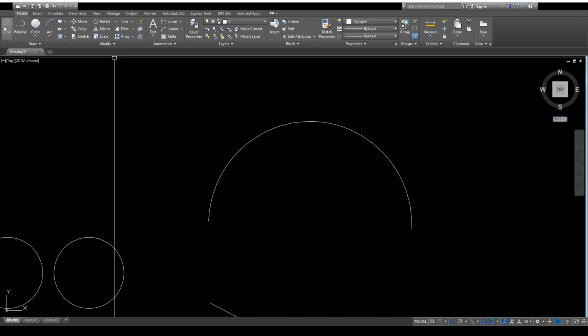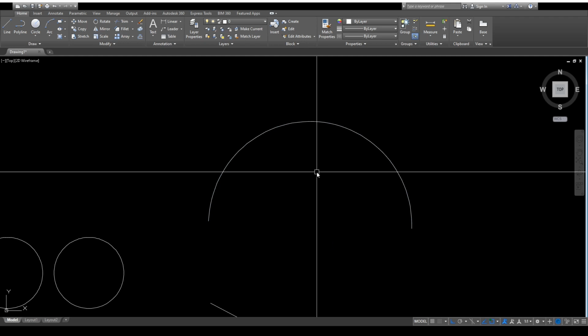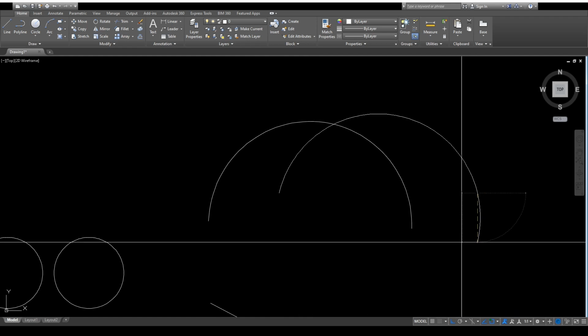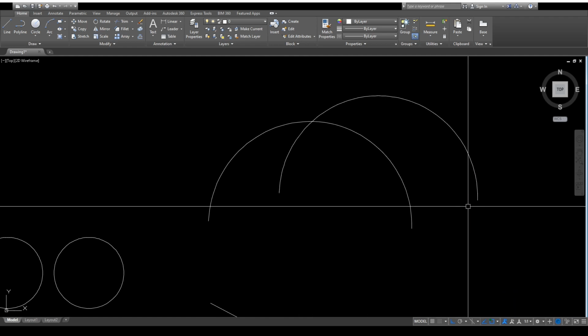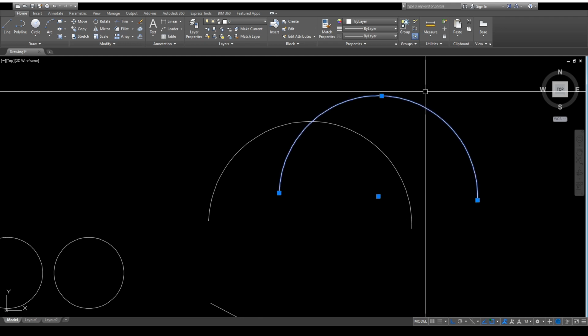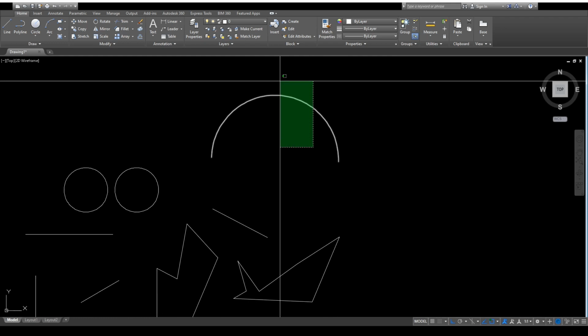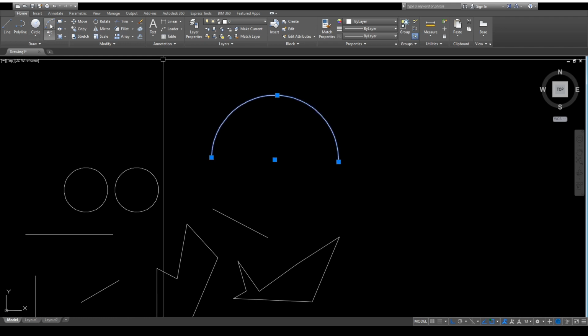So we've covered 1, 2, 3, 4. The shortcut key for arc is, if I'm not mistaken, arc. Or AR. No, it's arc. So, you type arc and then, there. It's not really a shortcut. The command key for arc is ARC. Similar to this one.